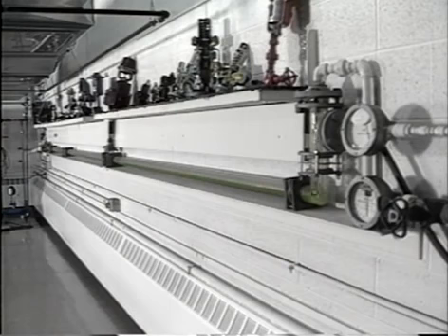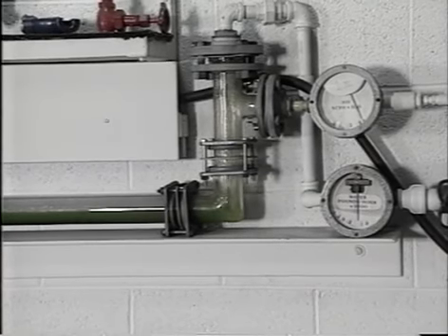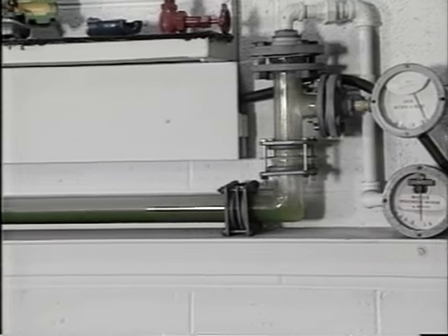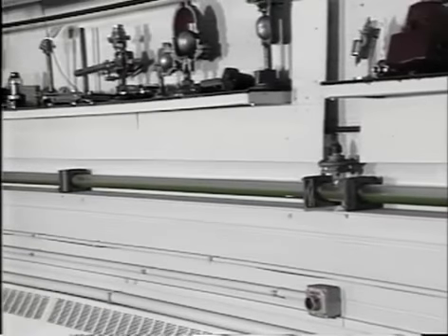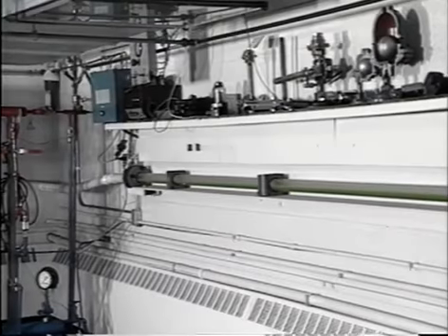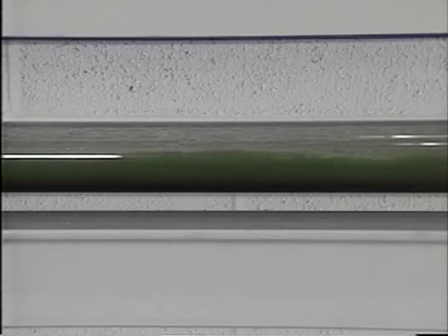In the demo lab at Armstrong International, we have assembled a fixture to illustrate the problem. We use this 20-foot, 2-inch diameter glass pipe to act as a condensate return line. The pipe is pitched 1/4 inch in 10 feet to provide gravity flow. Flowing through the pipe, we have cold water. In addition to water, we can also have compressed air flowing in the system to simulate flash steam flowing across the top of the condensate by virtue of differential pressure.